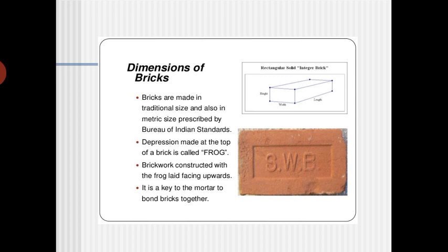Whenever that frog portion is there, you should take care when you are placing that frog face, because that face itself will bind to the mortar, and the mortar is going to join the two faces of the frogs.